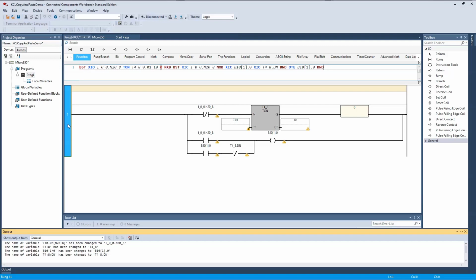from Logix 500. And you'll see this rung doesn't look exactly like what we were just looking at in Logix 500. So there's some work here that needs to be done. You'll note there's a number of little yellow warnings that need to be resolved. This extra data that's kind of floating out here. So it'll get you the structure of your code, but there's still going to be some work on your part to correct all the data to make it work in the actual program. So it's a little bit better than maybe having to manually type everything in, but it's still going to take some work. You know, similar to what we had with the import function that we previously looked at.